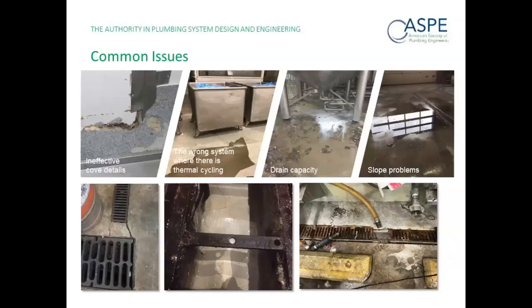Anytime you have a 90-degree angle in concrete, it's not if it's going to crack, it's when. And it will crack on a diagonal. So if you're using square drains or square area drains, I would just caution you need to have relief from those in terms of the correct details, because they will crack over time. The way to get around that is using round drains or better trench drain systems in general.